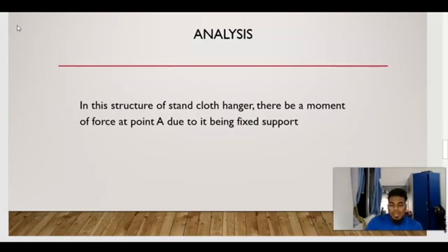I'm going to explain about fixed support, which has a few reactions. A rigid or fixed support reaction resists both rotation and translation, so it can resist types of forces and movement, and as we know, it provides good stability to the structure. Madam, the second point is that at least one rigid support should be provided to the beam, well fixed in the wall, as we know in a free body diagram. The beam is fixed and the wall is a good example of fixed support. That's all from me, madam. Thank you.